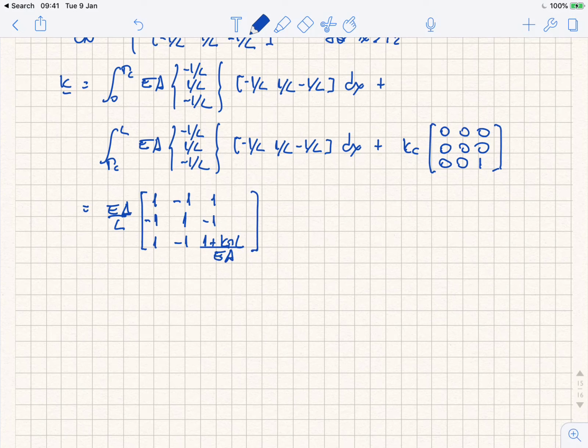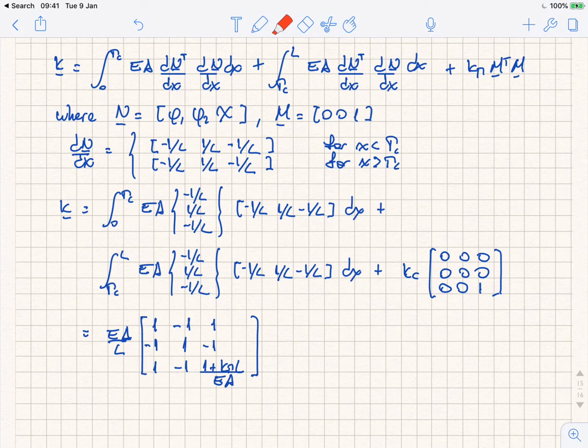It's just simply carrying out all this math, but you get that stiffness matrix, okay? And if you see, it was very simple because the only thing we need to do is to add the enrichment at the back of our array that contains the enrichment functions and shape functions, and we just define this matrix M to provide the coupling given by the spring at the location of the discontinuity. So this is the stiffness matrix you get.